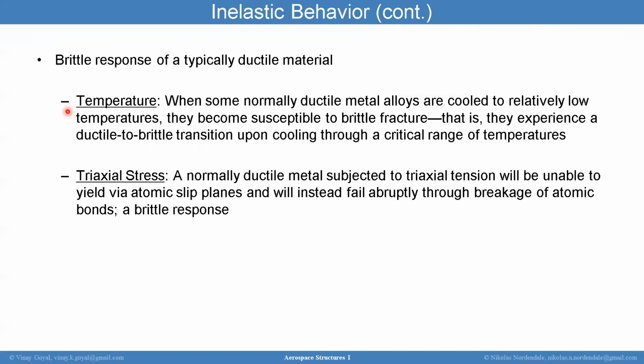One of the most common ways is temperature. If you have a very low temperature, we're talking cryogenic temperatures, liquid hydrogen, liquid nitrogen, liquid oxygen, those very cold temperatures, they can be susceptible to brittle fracture. Essentially, when those very low transition temperatures occur, typically the energy of your atomic bonds has dropped such that shear failure is no longer enabled. Basically, the material can't shear in the same way, and you overload the atomic bond in tension. So you have a metallic material that, if you drop its temperature enough, can fracture in a brittle way.